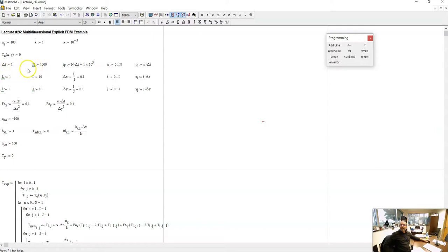The reason I define this differently, rather than starting by saying I want to know the final time of arrival, is because I want to control the Fourier numbers. Remember that in theory, and in practice too, the Fourier numbers in an explicit scheme would have to be below 0.5 for the scheme to be stable. So I want to make sure that the delta t that I pick and the resulting delta x, delta y will provide me with stable Fourier numbers.